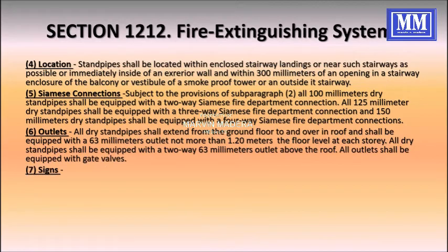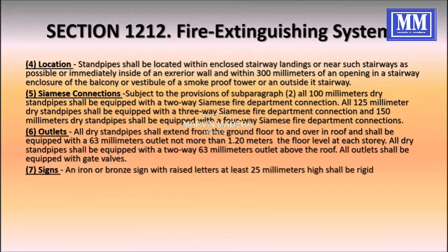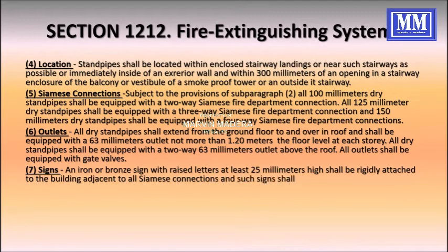Siamese connections are subject to the provisions of subparagraph 2, and all 100 millimeter dry standpipes shall be equipped with a two-way Siamese fire department connection. All 125 millimeter dry standpipes shall be equipped with a three-way Siamese fire department connection, and 150 millimeter dry standpipes shall be equipped with a four-way Siamese fire department connection.